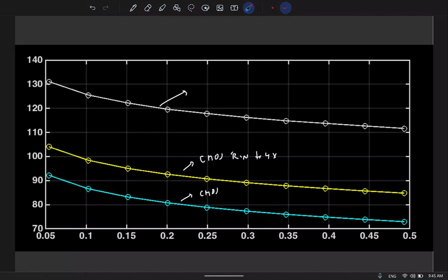See, if you are looking at very low speeds, that is, the frequency fs by 2 will be really small. In that case, remember that for a CMOS switch the problem was making omega naught Ron C to be much smaller than 1, right? If you are dealing with really low frequencies, omega naught, you can basically size the CMOS switch to get the Ron to be small and get the required linearity. It all depends on application.